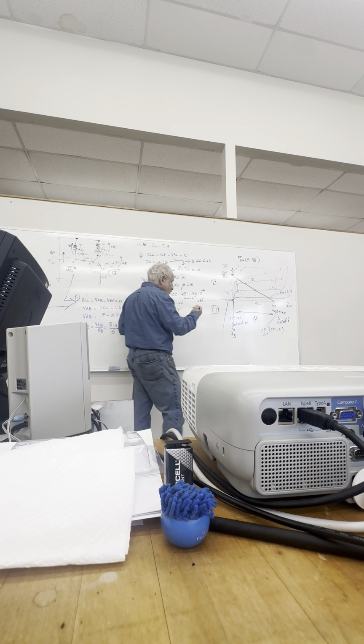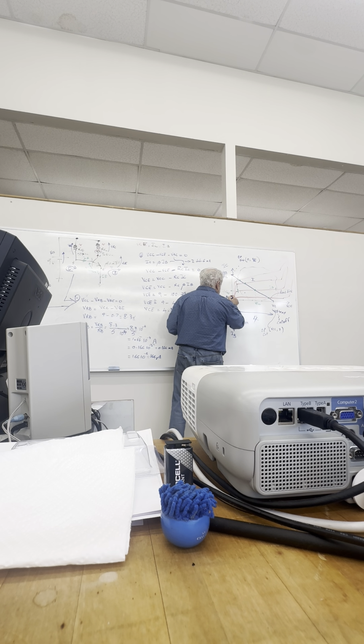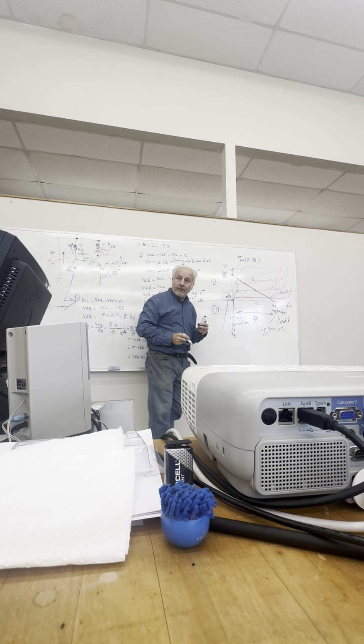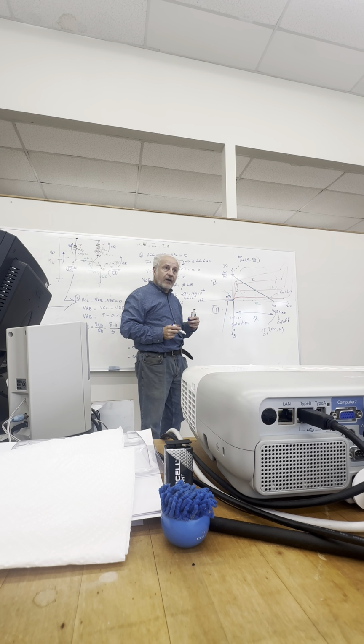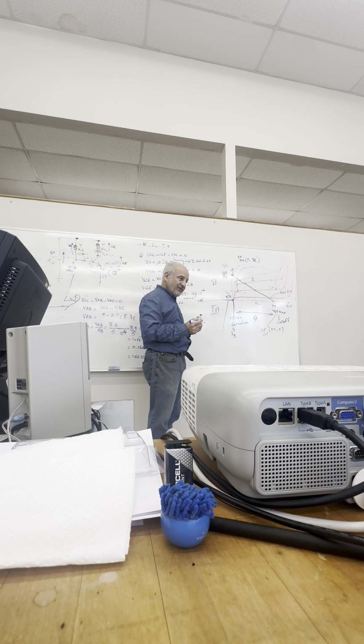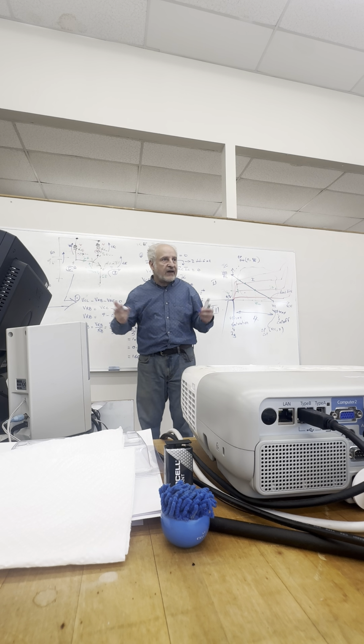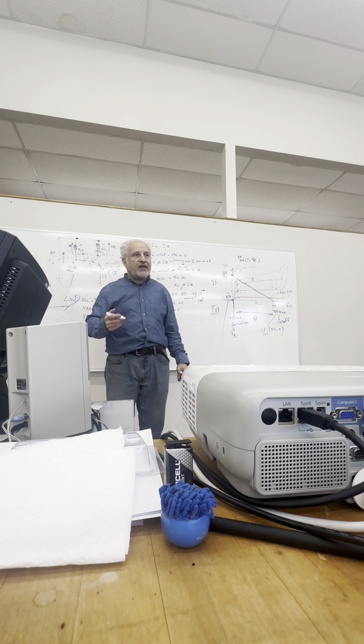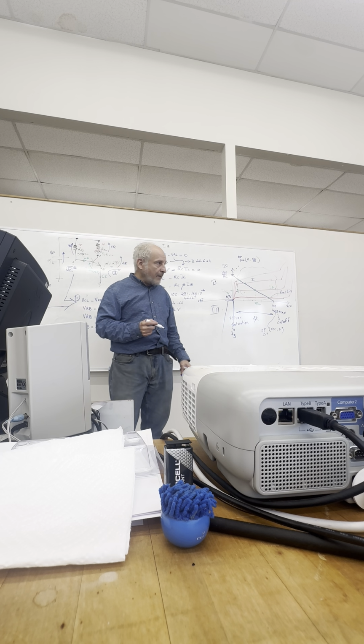And you will see this curve here at what? 0.7 volts. Oh, for the graph? Right. At 0.7 volts, it'll just, boom, just like a diode. It's a junction between the base and the emitter. Does that make sense? Yep.